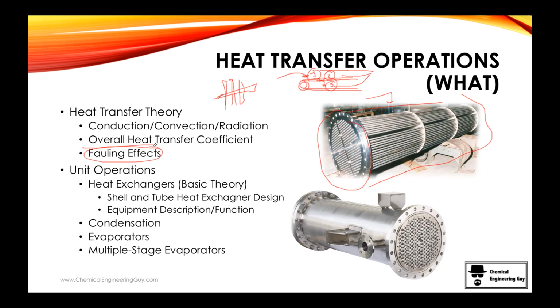Now we have also fouling factors, which is a very common practice, especially when we have high temperature. It's when small little things start to, let's say, attach to the wall. So you will experience higher speeds because there's less space, and higher drops of pressure, which means higher friction, which means more money. So you will want to avoid that.